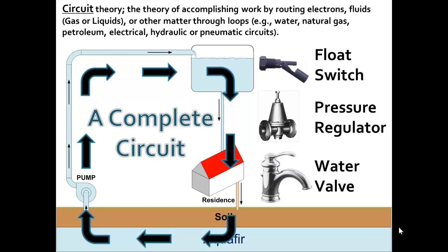The water in your hot water heater, that's strictly water pressure. And that's good because you want the water pressure from the tower to be felt all the way through the hot water system to your hot water valves on your sinks and shower. That way you've got water pressure for the hot water. So it's the cold water pushing on the hot water in the hot water tank that pushes out the hot water for you to use.